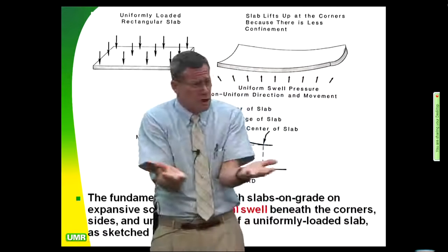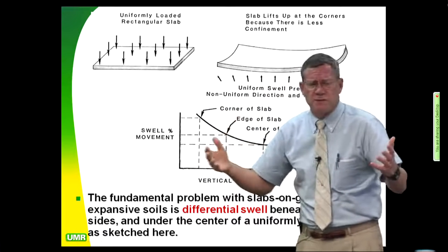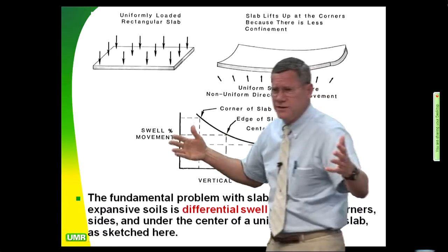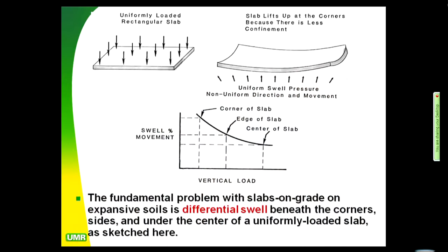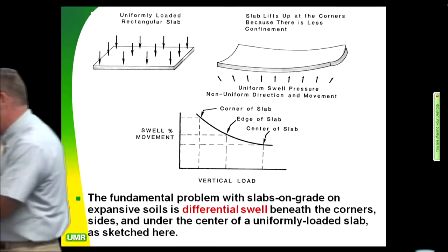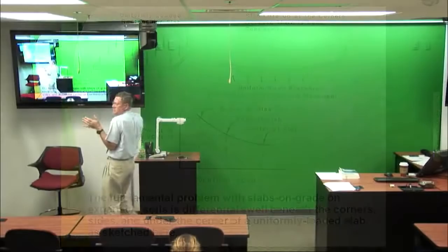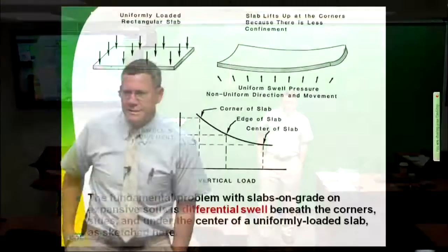Now that's the heaviest structural loads you're ever going to have. If I took all of us together, and I used to do this before political correctness came in on us, but I got all the boys and girls and pushed us all over here in the corner together and got real close. And then I asked you for all your respective weights, which the girls don't usually give, but anyway. And we added up all of the weights, and we divided by the triangular area here that we're all squished into. We get about 35 PSF, 35 pounds per square foot. That's not a hard thing to design for.